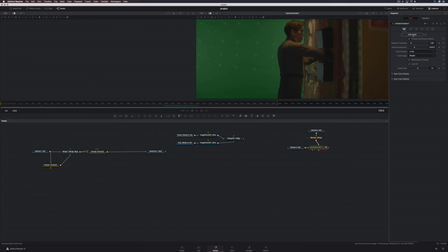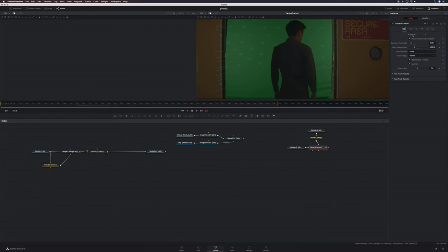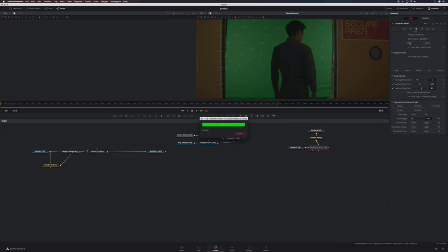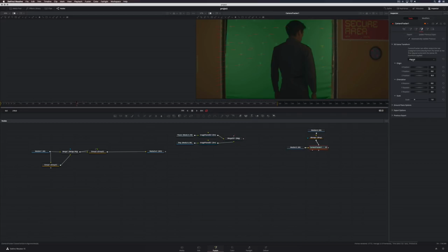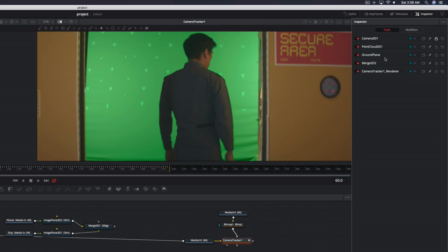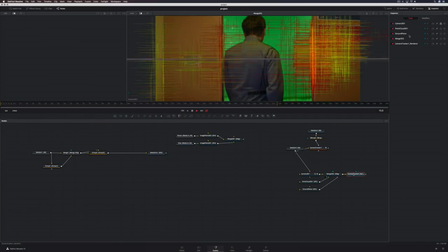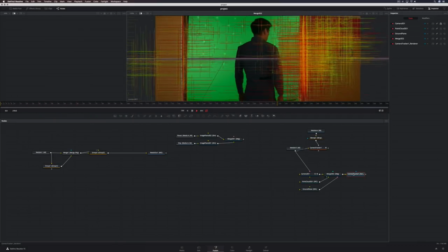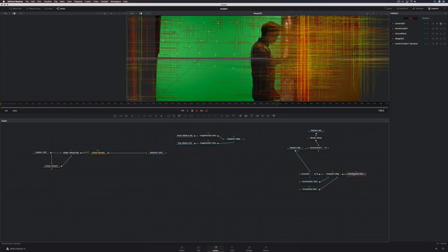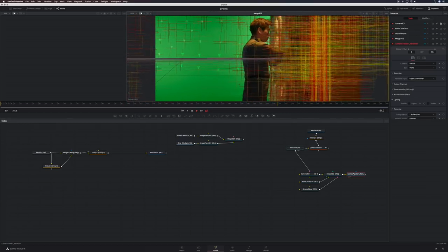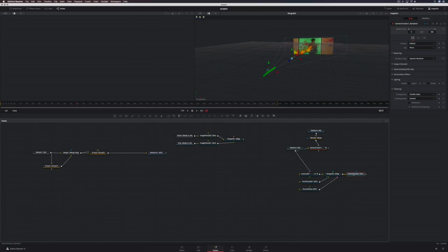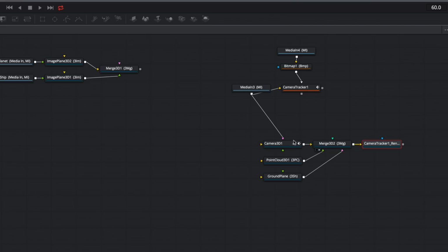Once your track is complete, the next step is setting up your camera to match how your footage was filmed, to solve for a proper track, followed by 3D solving your tracks into 3D space, and lastly, we're ready to export. Fusion creates a point cloud, a ground plane, a render node, and a keyframed camera that matches the movement of your footage. Although this process is straightforward, you should allow proper time to let each step process based on your clip. So with our camera solved, let's connect the camera node to our Merge 3D.